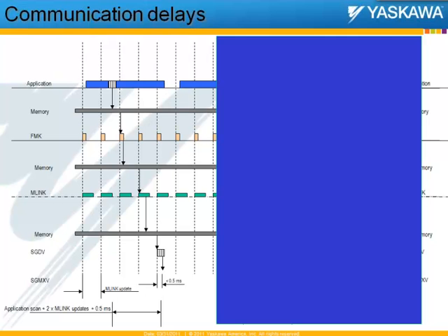The practical implications of this are seen on very high-speed registration-based machines where a master could have moved a significant distance in 1 Mechatrolink scan. And this can lead to labels being misplaced in a labeling machine, or on rotary knife applications which have registration, the cut can be at a different location, because if the master has already moved and you're making decisions late, then your slave is commanded to work on a later position, which essentially leads to inappropriate cuts for rotary knives and inappropriate labels for labeling machines and so on.